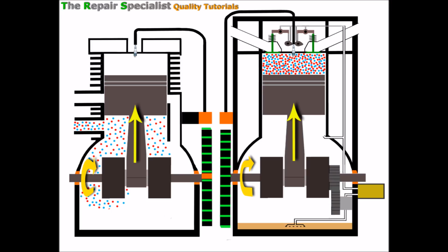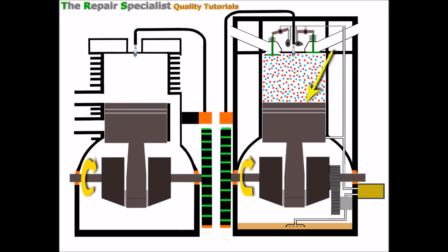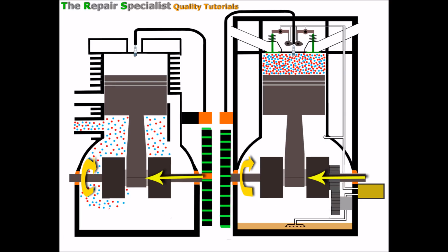And if we take a little snapshot now of the position the components are in, the crankshaft has moved from its lowest position and rotated 90 degrees further. And this of course has allowed the pistons to travel halfway up their travelling distance within the cylinder. And now things are starting to look a little different. With the 4-stroke engine, we can see there that the inlet valve is now tightly closed and nothing can go back past it, and it's the same with the exhaust valve.